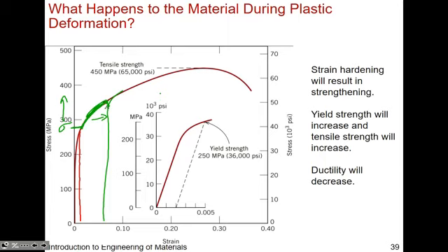Yes and no. So yes to both. I agree with that, because this is an imperfect example of introducing dislocation. I think the better and more consistent example would be what you've seen with necking, where you're just elongating and then you actually reduce the cross-sectional area, and that's when it starts to neck. So when you recalculate the force over area, you're actually dividing by a small area, so your strength actually increases.